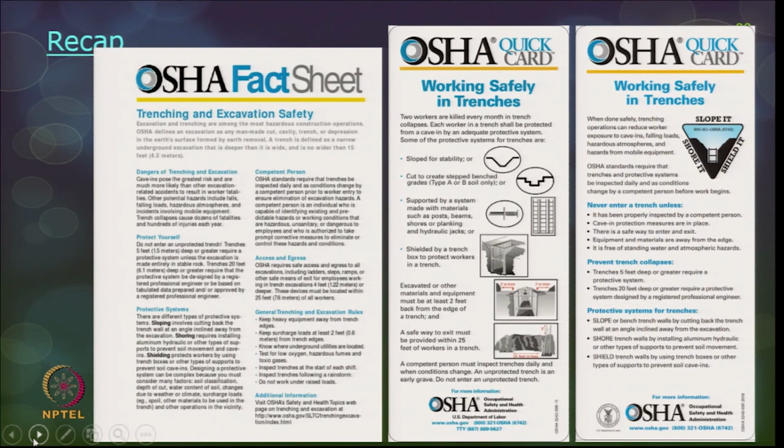And there are also a lot of OSHA fact sheets and quick cards on working safely in trenches and doing excavation works safely. For example, never enter a trench unless it has been properly inspected by a competent person, cave-in protection measures are in place, and there is a safe way to enter and exit. Equipment and materials should always be away from the edge, and the trench should be free of standing water and atmospheric hazards. Prevent trench collapses. So, trenches 5 feet or deeper require a protective system, and trenches 20 feet or greater require a protective system which is designed by a professional engineer.